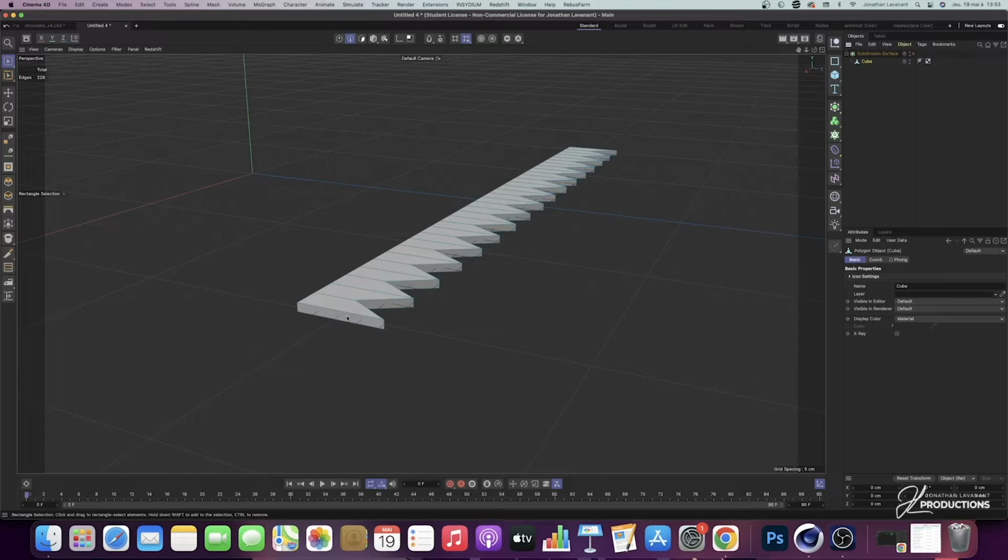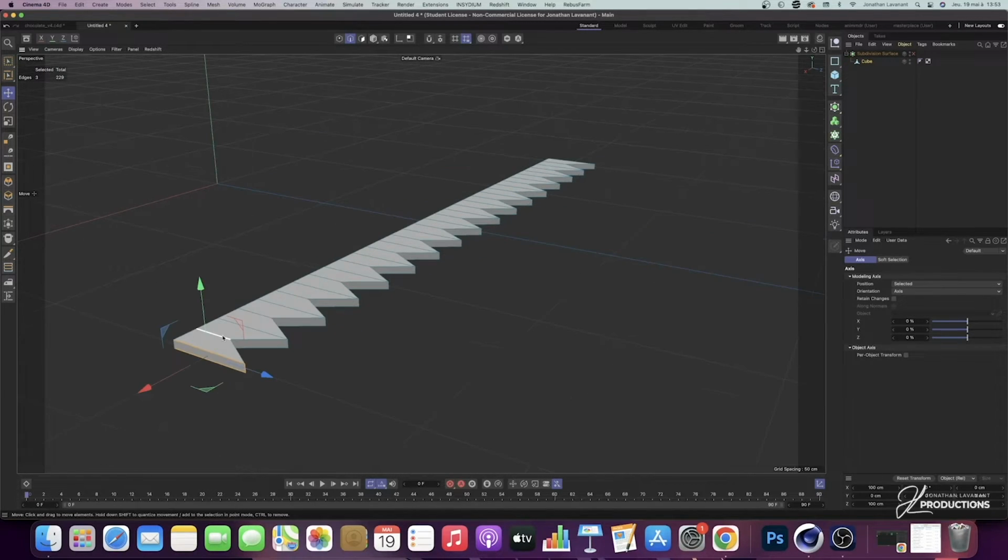I select in cubes and come and select edges, so here on the edge, you select the 3 that are there. So to be able to add more selections, you press shift to add the selection and double click to be able to select the whole loop here.